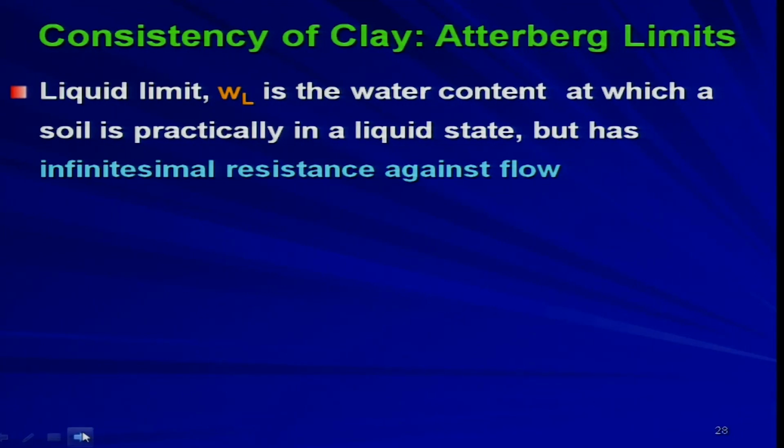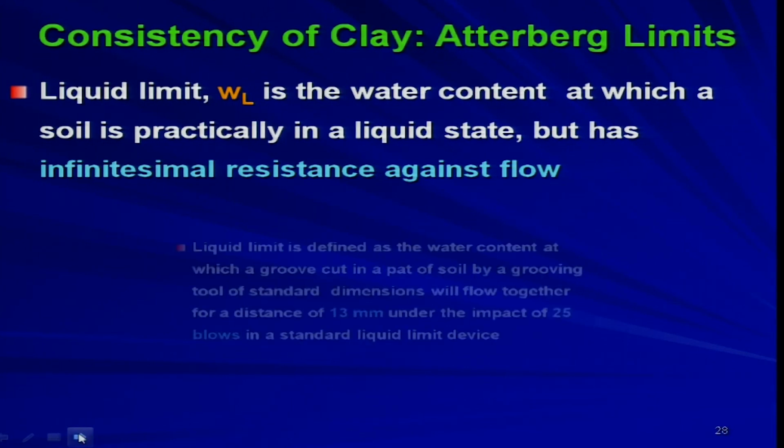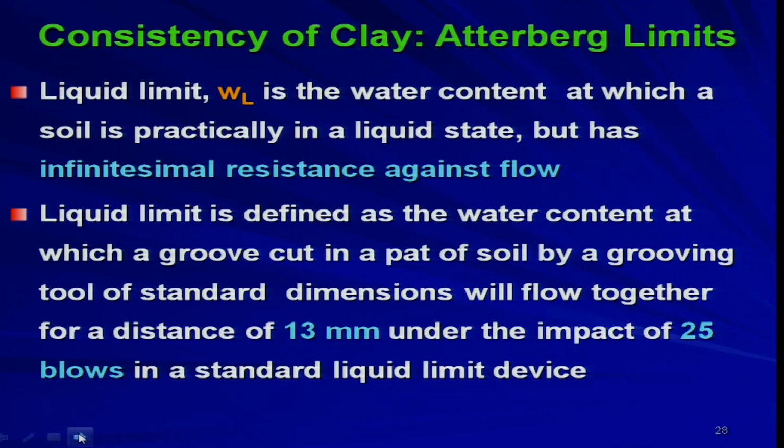Now, liquid limit can be defined. It is generally represented as WL and it is defined as the water content at which a soil is practically in a liquid state, but has infinitesimally small resistance against flow. So, basically you do not have any resistance to the flow. Liquid limit is defined as the water content at which a groove cut in a pad. So, this is again related to your laboratory experiment.